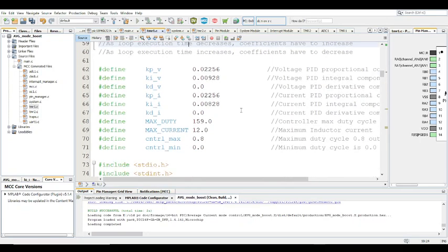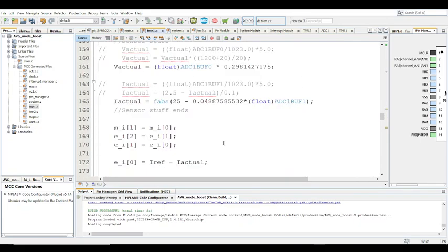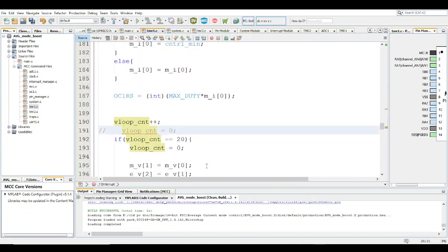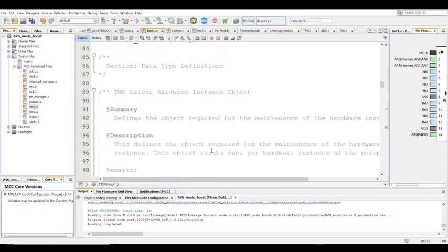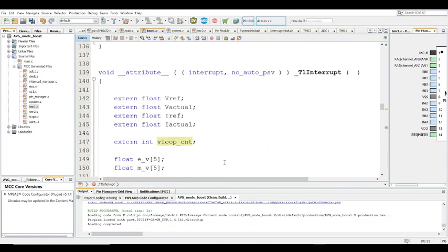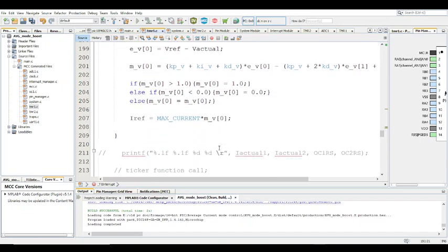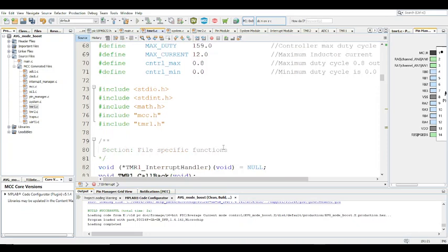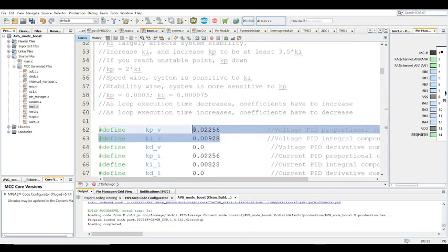Yeah. So that's that. So after you've confirmed that it's working just fine, then you can uncomment this and include the outer loop, the outer loop voltage. And with the outer loop voltage, when you're just including it for the first time, you want to make it as slow as possible. You don't want to make it fast. So how do you do that? At first you increase slowly.